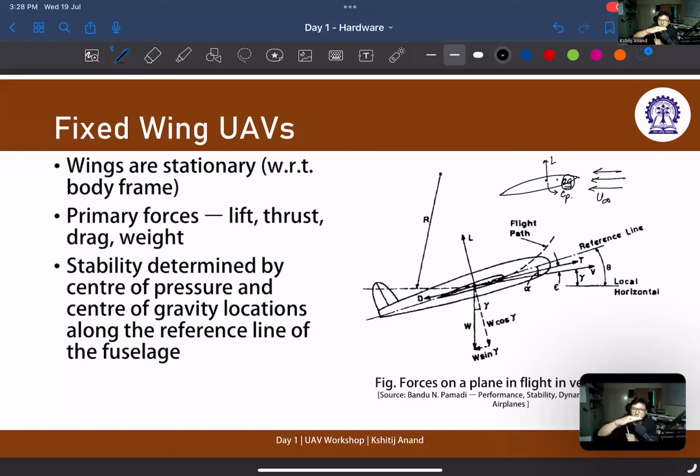If you do not need to do that, what is going to happen? The moment you apply force to put it nose up and it does not have a tendency to come back down, it will keep increasing its pitch, and that will lead to stall. We'll discuss stall later on. Stall is basically that you simply can't keep on pitching your airfoil all the way up and expect the aircraft to fly.